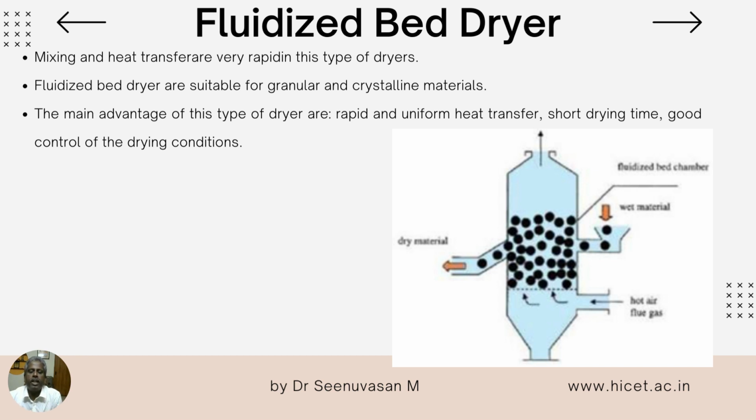Before entering into the fluidized bed dryer, try to understand the difference between the fixed bed and the fluidized bed. Fixed bed: what is a fixed bed? Whenever the fluid is flowing against the packing material, the bed becomes stationary; the packing material does not move along with the fluid. That is called a fixed bed. In the case of a fluidized bed, when the fluid is moving, the particles can move along with the fluid. That is called a fluidized bed.